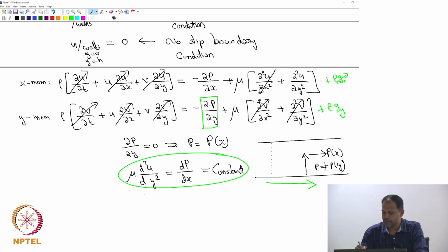So, let us say that this is called a dynamic pressure, that means we have already removed the hydrostatic part from it. We will call it PD, then it is okay, and that is because gravity will not do anything. But if you were looking at a pipe which is perpendicular to gravity, then you should have been careful, because these two components will add up in the same direction now.